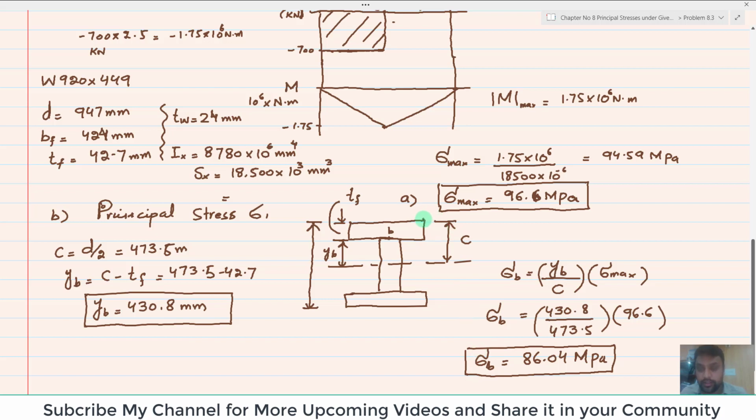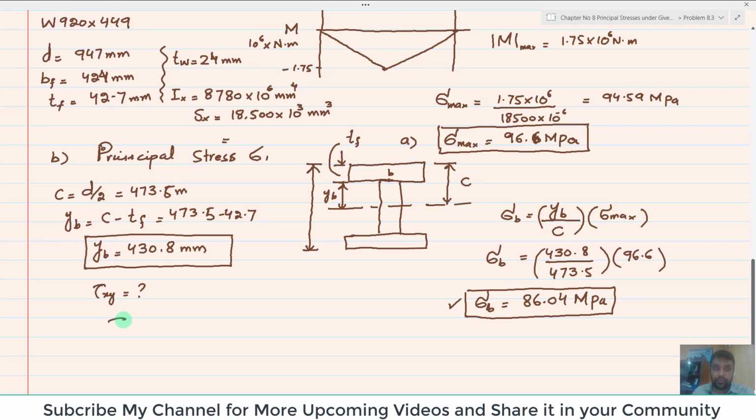Clear? Now you have this sigma B, and again for finding principal stresses we have normal stress at this point, but we do not have shear stress tau of xy. So for tau of xy we will calculate the shear stress. As we know, this is equal to V max into Q divided by I into thickness of web.